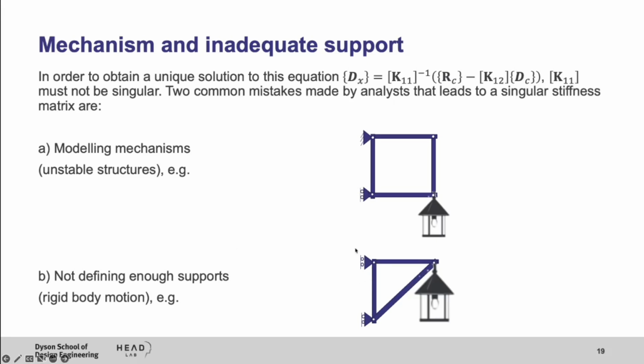So imagine here, if I just replace that pin joint by a roller joint, this support will start falling down, okay? And therefore our structure is not in static equilibrium anymore, and the software will not be able to solve this problem. If you do not believe me, I would actually strongly encourage you to model both structures and see what you get from the solver.